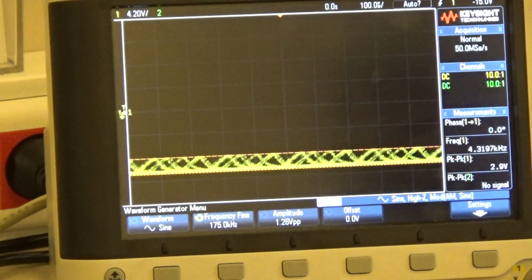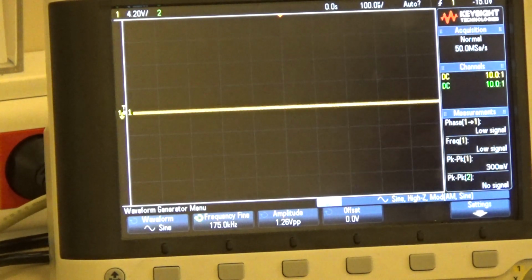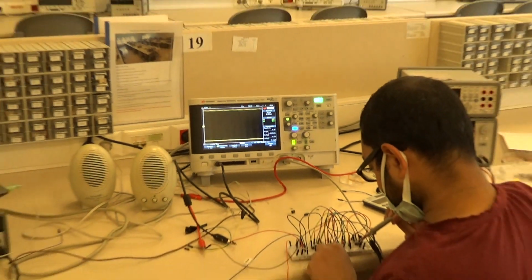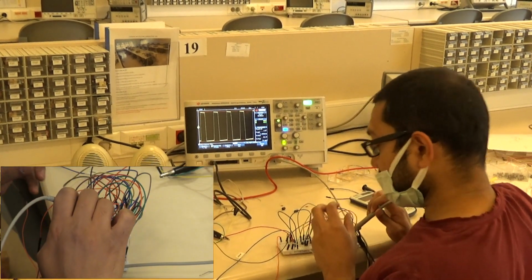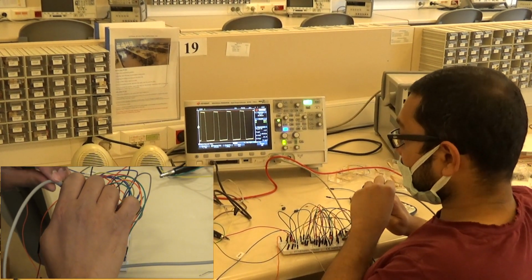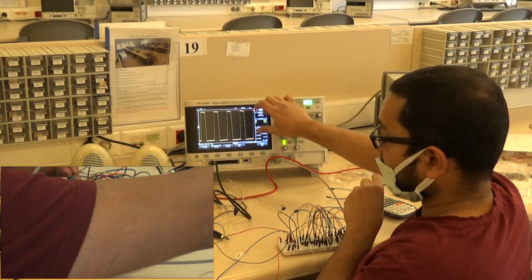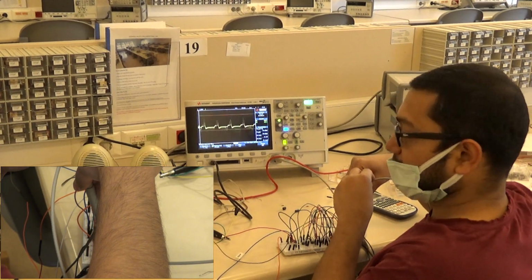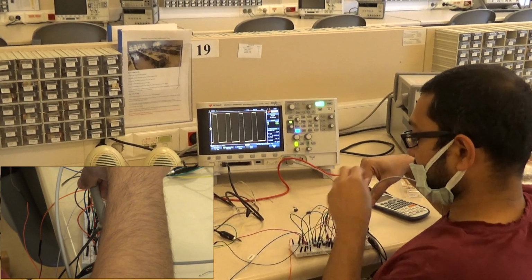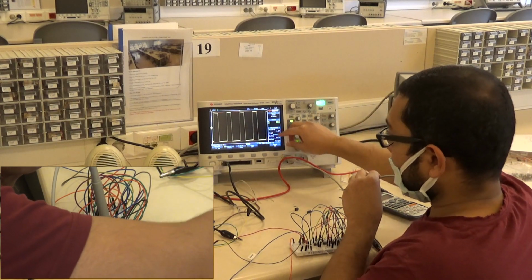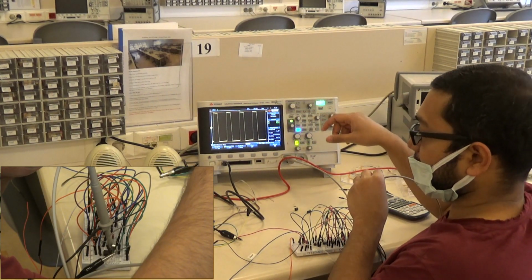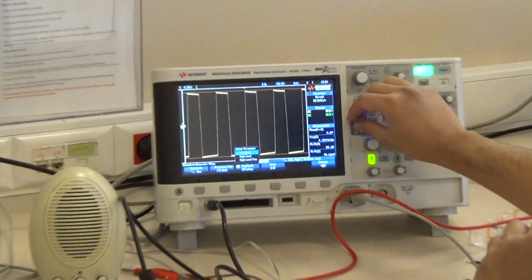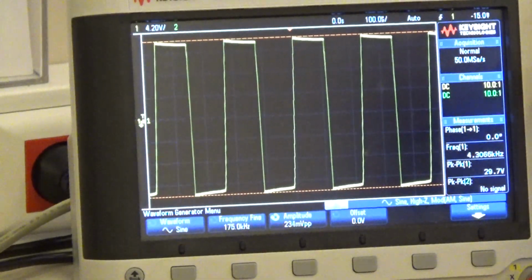Now after this I'm going to amplify it. I've used a very large amplification because the audio signal coming from outside needs to be amplified a lot, that is why it is clipped in this case. When you connect it with an audio signal, since the voltage is very small, it will not be heard properly. That is why I have made sure that it clips off properly. If you want to check it, you can just reduce the amplitude of the input signal, but since I have clipped it, I have provided a voltage such that it clips.